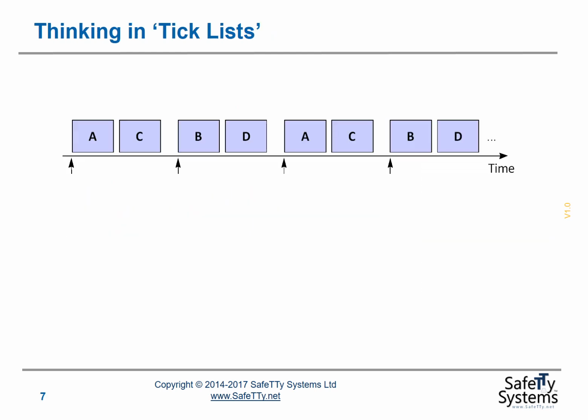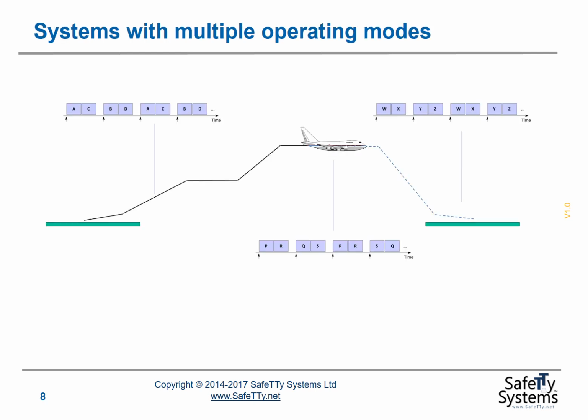We talked about the importance of thinking in tick lists when you create your TT design, and we've talked a lot about tick lists during this course and seen that these are a key way of modeling time-triggered systems. We've seen that systems may have multiple operating modes, and in each operating mode, they're likely to run a different set of tasks, have a different tick list.